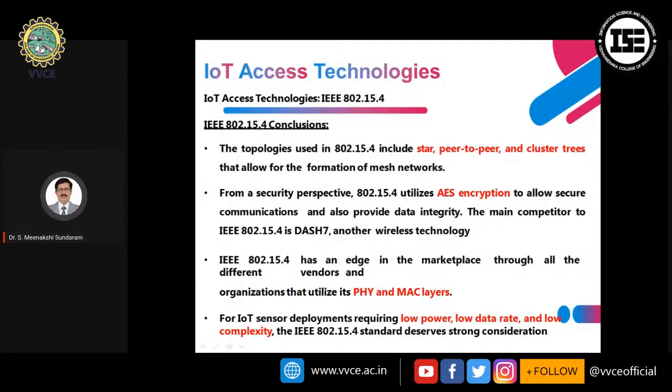From a security perspective, 802.15.4 utilizes AES encryption standards and has an edge in the marketplace, as all the different vendors and organizations utilize this physical and MAC layers for building various applications. IoT sensor deployments require low power, low data rate, and low complexity.